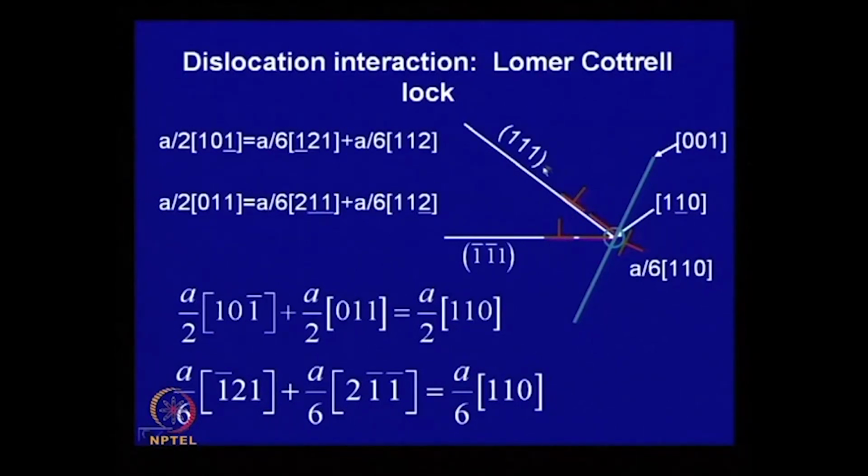So, that means whenever this type of lock is generated in the crystal, it makes dislocation movement difficult, or it makes the material stronger. We call this, in technical terms, the material undergoes strain hardening.